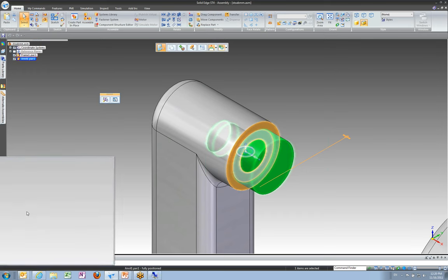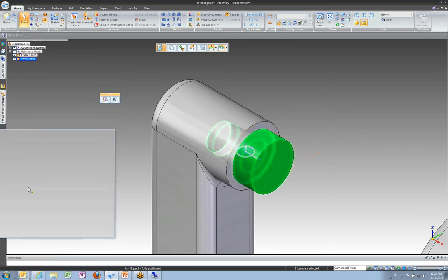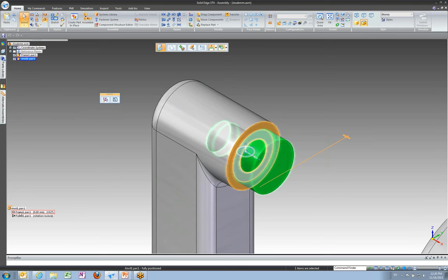That little icon next to the assembly relationship, I've got to find it with my magnifying glass here, tells us that that's a mate. Those are two faces mated together, and basically it's that shoulder of the anvil and the leading face of that frame there. They're both highlighted.